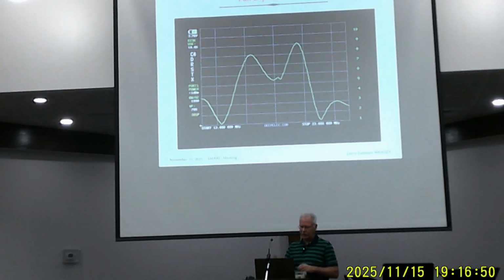Again, it doesn't apply to anything else like this. And again, that's not just the NanoVNA, that's this or anything else. You need to know the velocity factor, which is how fast the wave goes down the transmission line. In the 301P, some of the older ones only did 100 sample points. This one has 50, 200, and 300, 301, because he counts both ends. Again, to get the best accuracy, you want the most samples. So that's another setting you set and kind of forget and never mess with again.